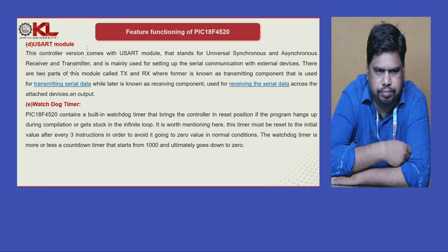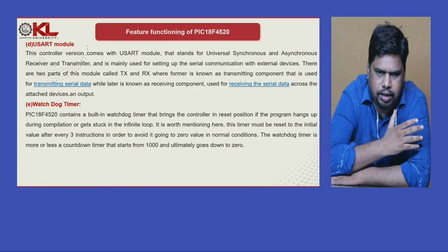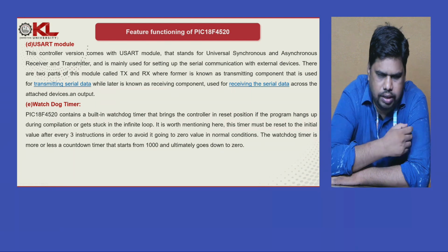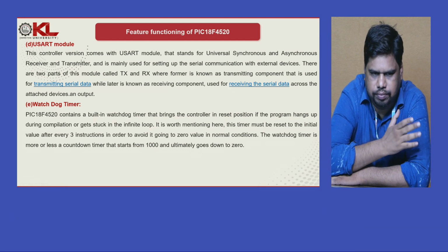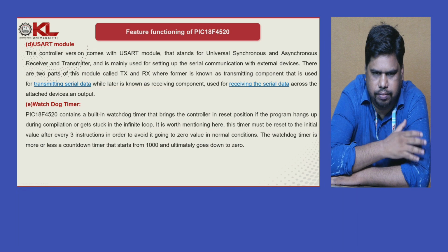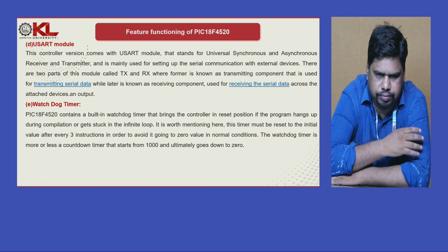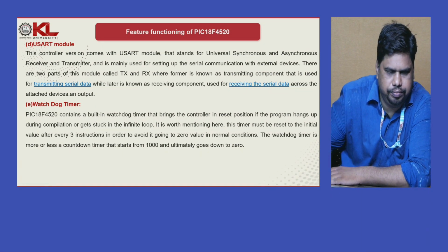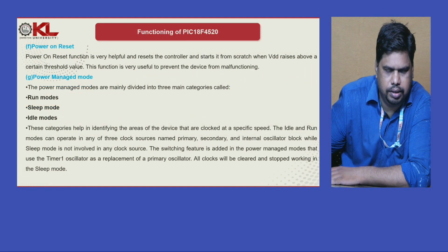If a program hangs, because we wait for an instruction to be executed in a pre-specified time duration and we are not getting a value, this watchdog timer will reset the program, and the compilation will start again. So this is the use of the watchdog timer here.